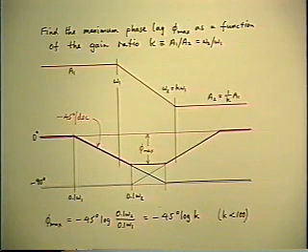It's very frequently used as a compensating network in a feedback amplifier. In a feedback amplifier, looking ahead for a bit, but you know it already, ensuring stability involves meeting the Nyquist stability criterion, which in its simplest form means that you have to prevent the phase lag from getting to 180 degrees while the magnitude of the loop gain is still greater than 1. Otherwise, negative feedback turns to positive with a gain greater than 1, and then you have an oscillation. So basically, the stability criterion is to prevent the phase lag from rising to the point of instability.